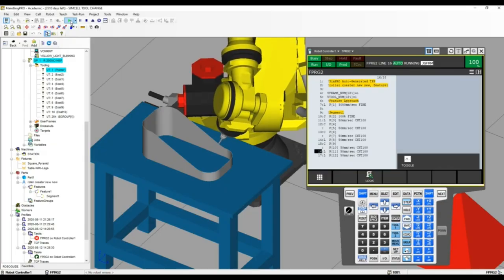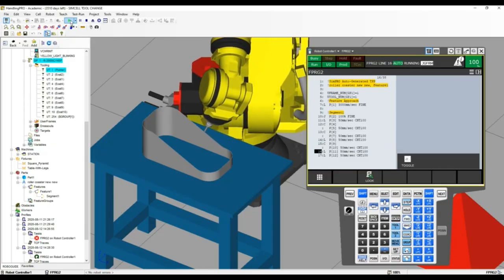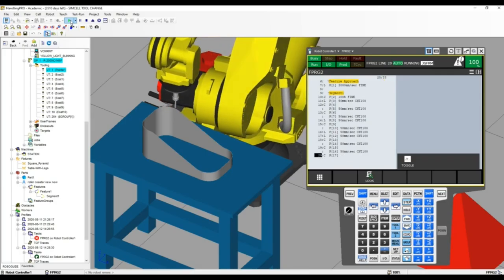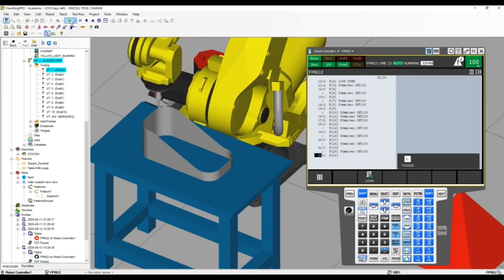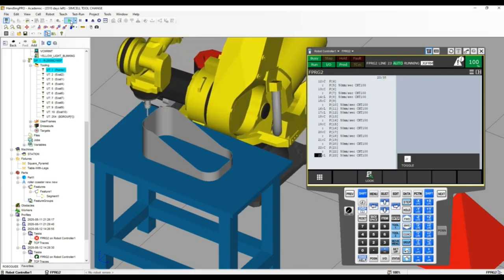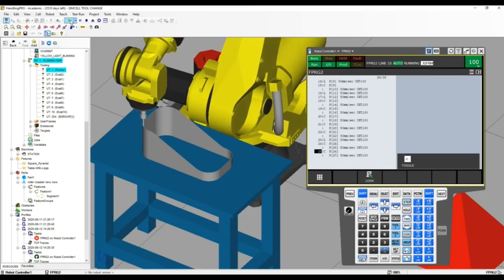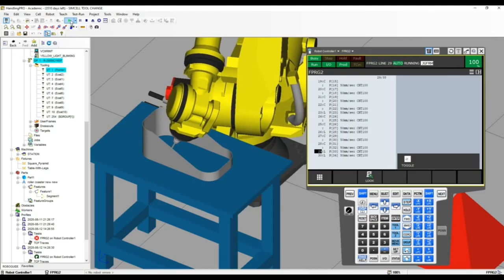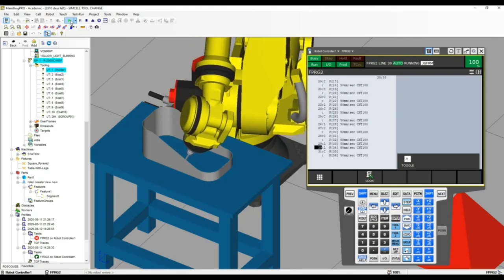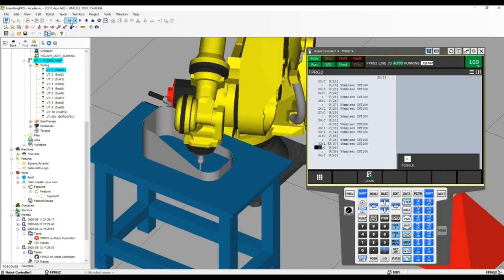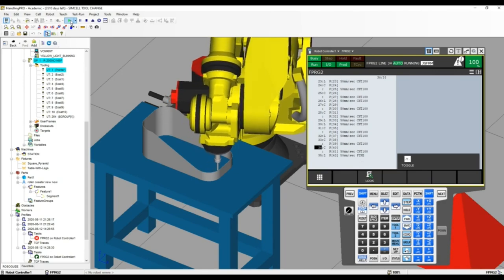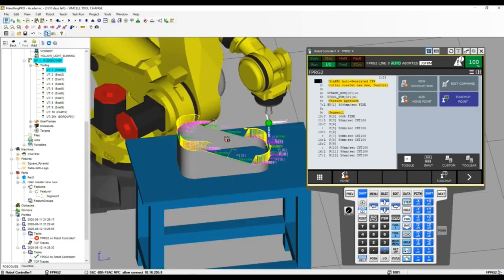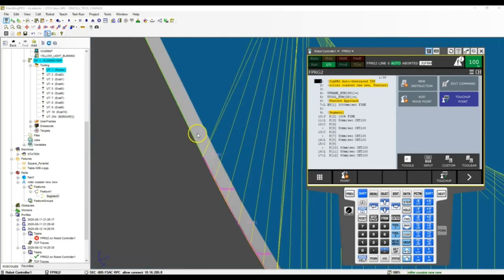So still perpendicular. So if we wanted that 45, all we had to do is move the table away. And we don't even have to reteach things. We just have to reset up the program to reset up the points in space. But you can imagine how much time this will save with weld paths, glue paths, or even testing. And there's our retreat.